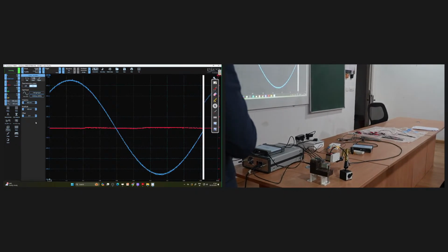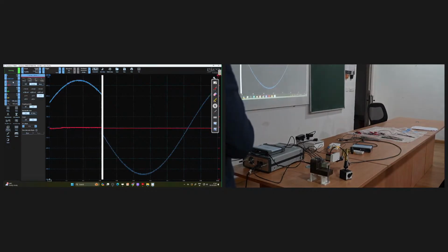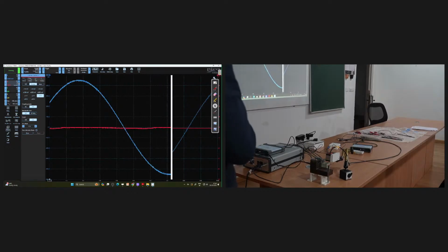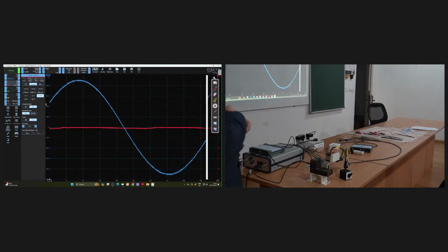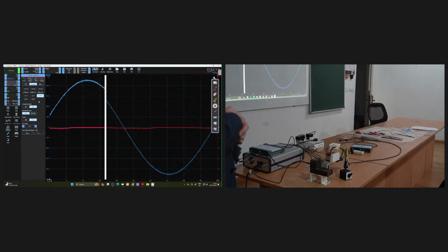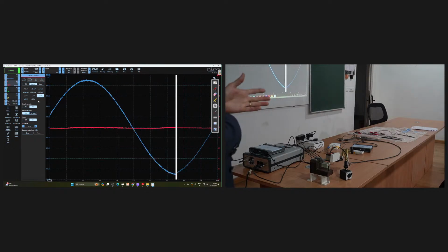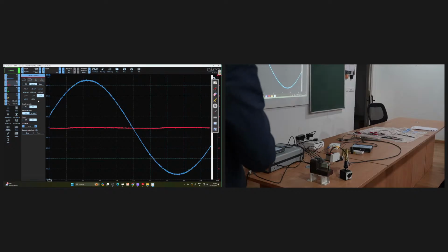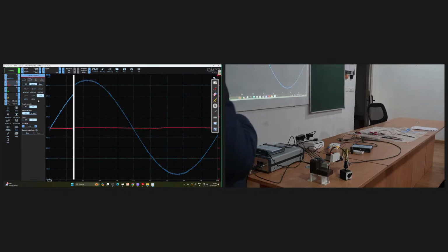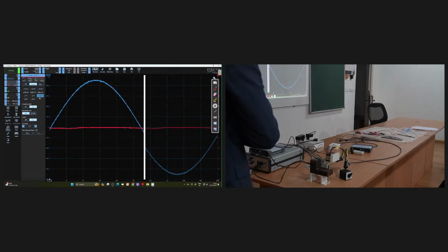Okay, nothing so far. Could you go to channel B, please? Channel B is, okay. So you can see everything, but the piezoelectric stack actuator only shifts by 40 micrometers maybe. So right now I'm showing 5 millimeters, plus minus 5 millimeters. So what you see is a very small signal. Could you change that to plus minus 100 millivolts, please?